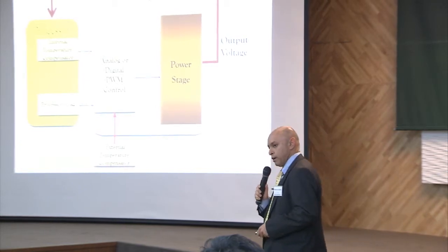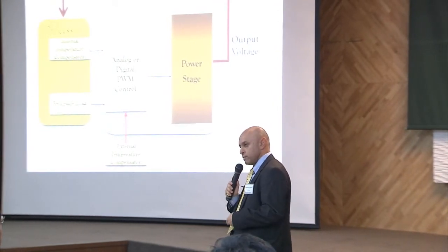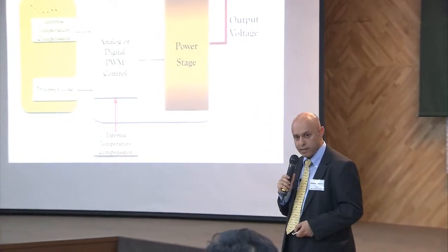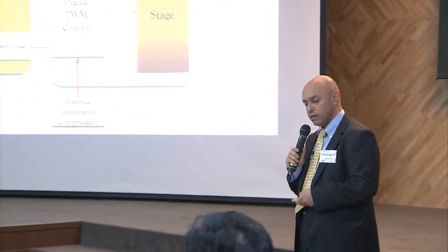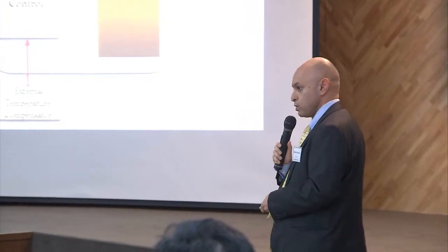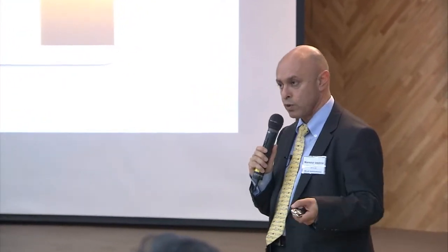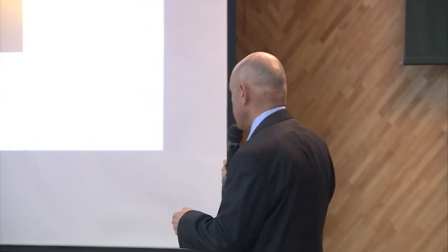In fact, as I pointed out, Intel, for example, back in 1995 mandated the SM bus communication, and one of the things that they monitor is the temperature. In fact, Intel was one of the early adopters of placing a temperature sensor onto their microprocessor. So here's a possibility. In this case, the processor has a digital PWM block actually integrated onto the processor, and in this case, the serial bus is now eliminated.